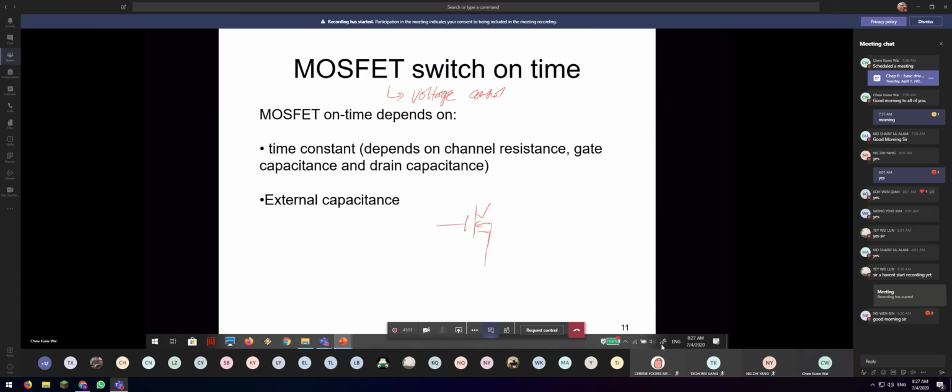Yeah, N-channel MOSFET, right? Okay, this is the MOSFET. The drain and the source will be cut off, there'll be no continuity. So here the idea is the gate: how to give the proper pulse, the proper voltage, so that it can turn on and turn off accordingly. So when the gate is high, it will trigger it to turn on.